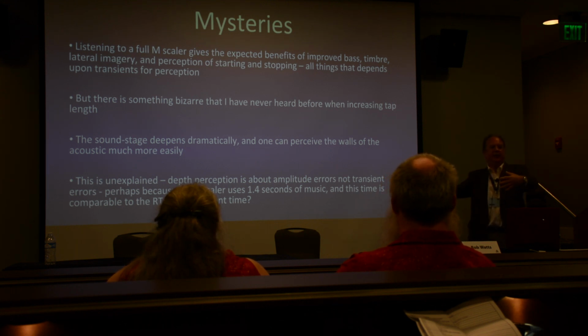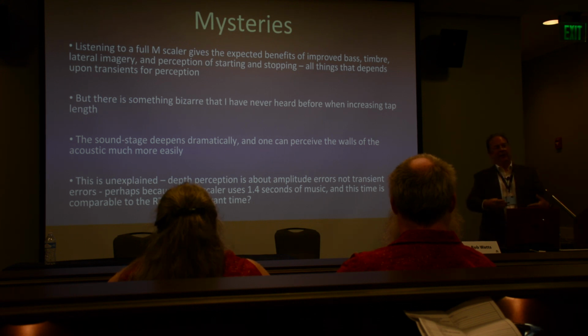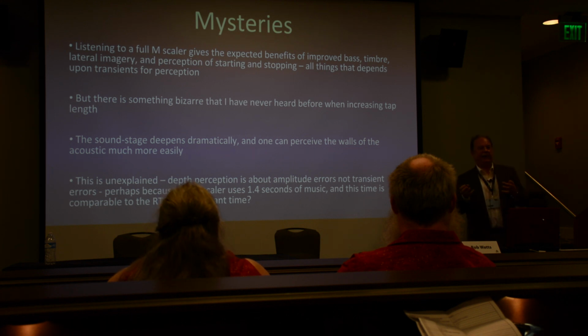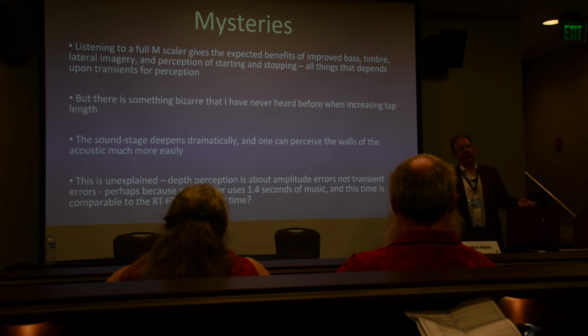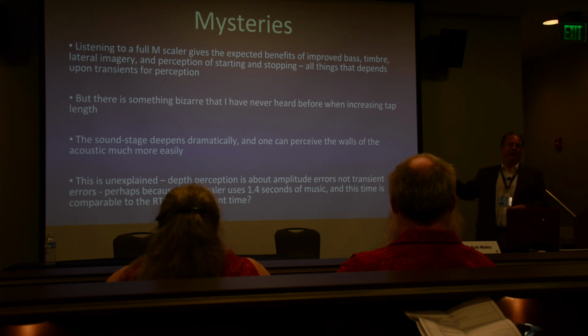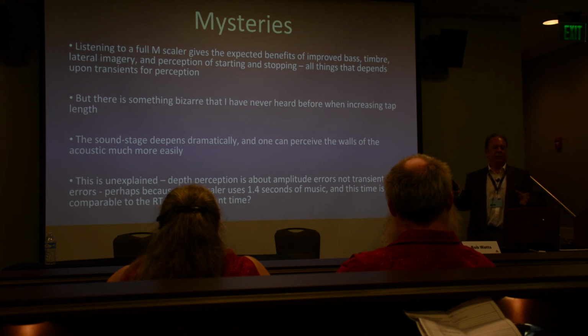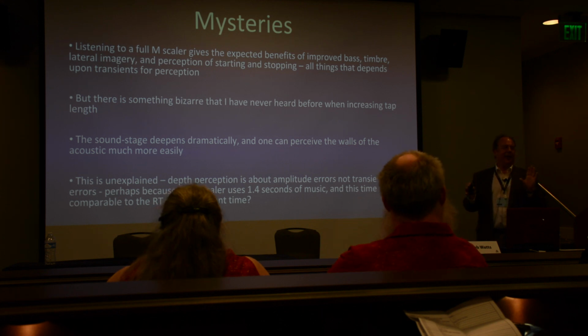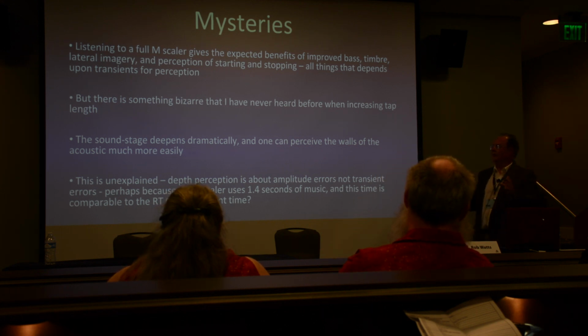The soundstage deepens enormously. That is very, very strange, because every single time I've changed an interpolation filter in terms of tap length and in terms of the WTA coefficients, the depth never changes. Depth is actually about a function of small signal nonlinearity. And small signal nonlinearity can occur within filters, but you can arrange that out by changing your architecture and doing things to the correct level so that you avoid truncation problems and blah, blah, blah. But that's a fixed issue. So it's very strange that depth and soundstage was so much different.